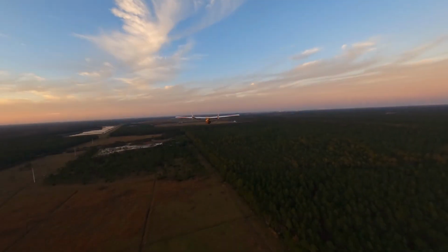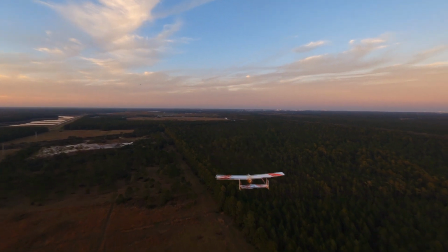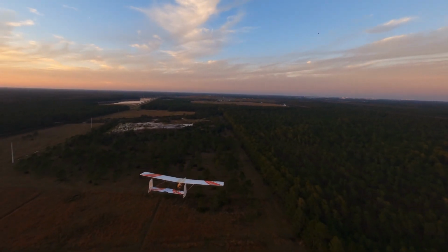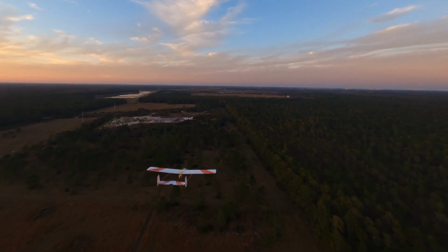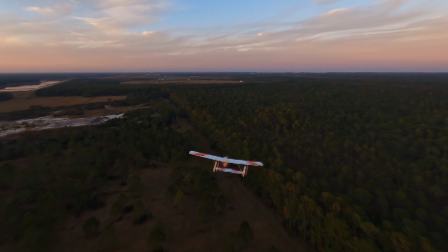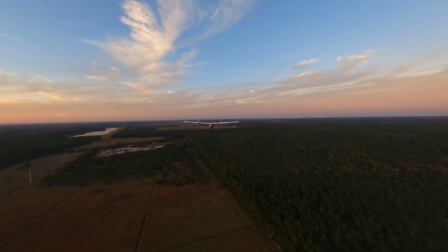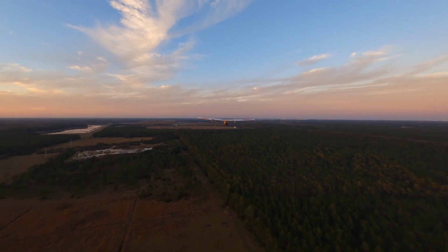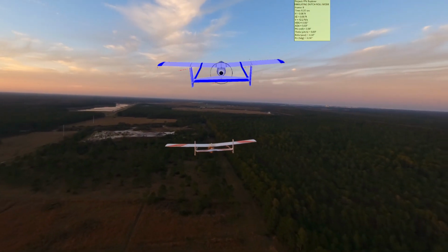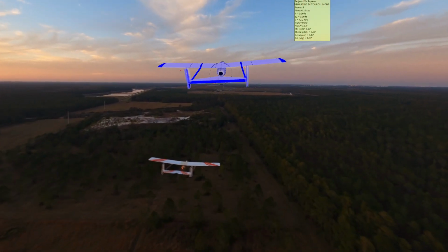Next, let's compare this to the real thing. Here's the FPV Explorer in flight. Note that the motion of the drone contributes to the visual effect. Also, despite my best effort at generating a step rudder input, the actual rudder deflection behaves more like a ramp input. Therefore, one should not expect 100% accurate similarities between the real and predicted motion. Rather, a qualitative comparison shows the motion to be reasonably close. See it again.